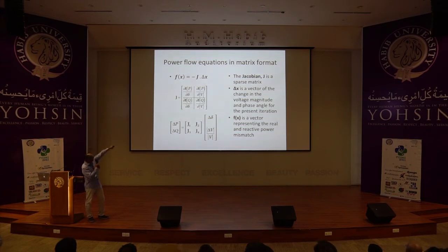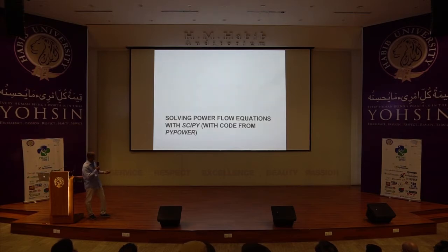No. So how that changes active power, you see, P with respect to the delta, and P with respect to the magnitude, and also Q with respect to the angle, and Q with respect to the magnitude. So whenever we change the voltage, it has an effect on the active and reactive power, and that tells us ultimately how we are going to serve the power system, okay? So this is what we want to solve.